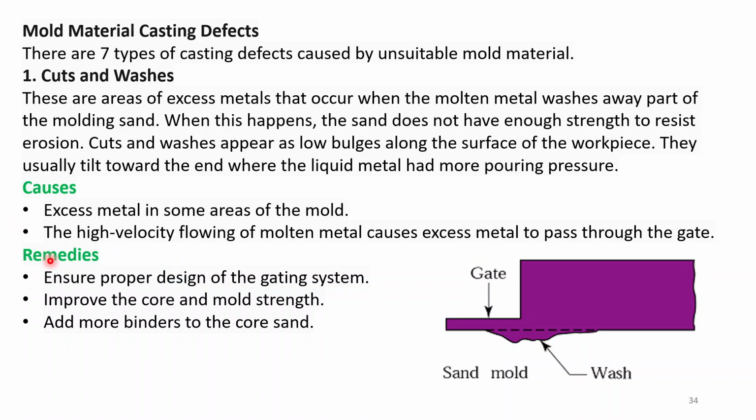So remedies: ensure proper design of the gating system, improve the core and mold strength, and also add more binders to the core sand.